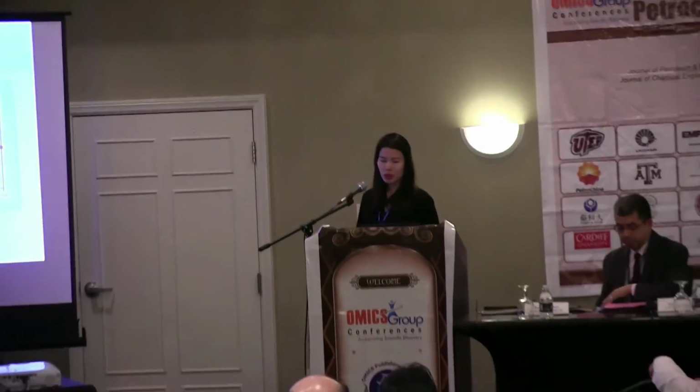Here are the results of our experiment. This is the oil recovery according to the polymer concentration. As the polymer concentration increased from 0 to 1,000 ppm, the oil recovery increased from 17.7% to 60.6%. So we can see that as a higher concentration is injected, the oil recovery is enhanced by this polymer solution. The oil viscosity ratio improved from 0.06 to 0.23.